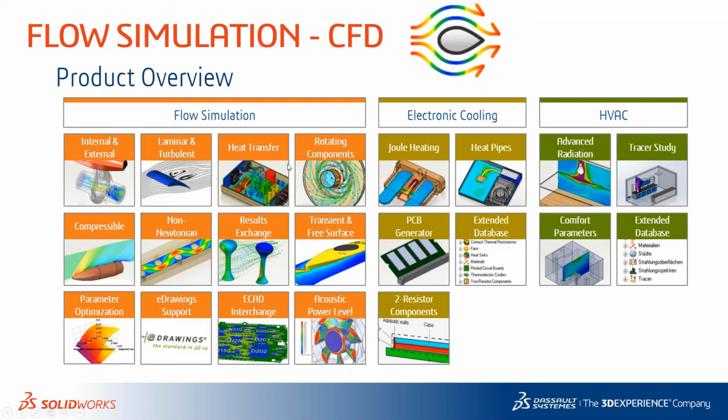And one of the great tools in using Flow Simulation or any CFD is in heat transfer, because the temperature affects the fluid properties and pressures and velocities, so it's very intertwined. There's 3 conservation methods which are solved using this Navier-Stokes solver: conservation of mass, momentum, and energy, and then you have your state equations of the fluid.